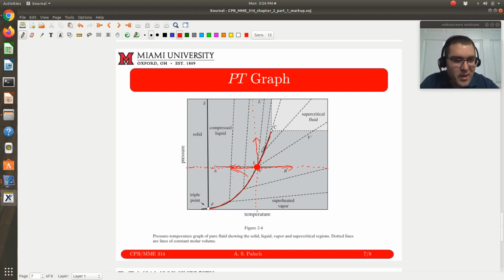Cool. So I have a line because liquid and vapor at equilibrium are at the same temperature and pressure. So I have a line, not a dome. Above, I have a compressed liquid. Below, I have a superheated vapor. You can go through the same thought exercise in terms of determining phases. And again, I often think high pressures favor liquid, low pressures favor vapors in terms of figuring out where I am on my phase diagram.